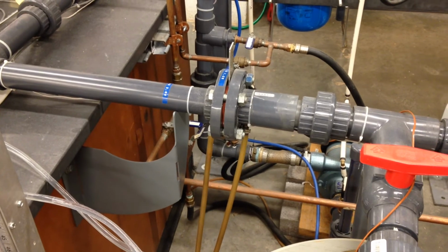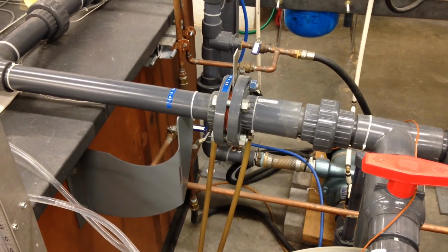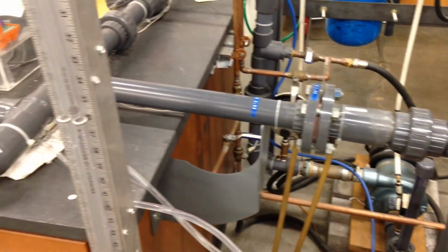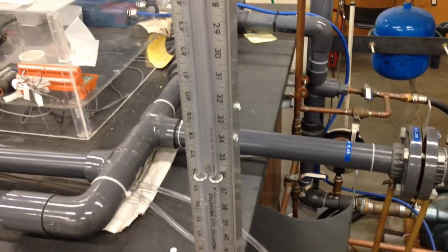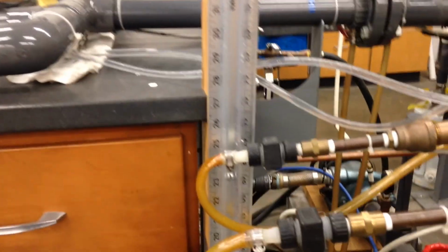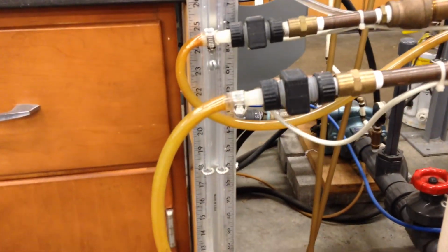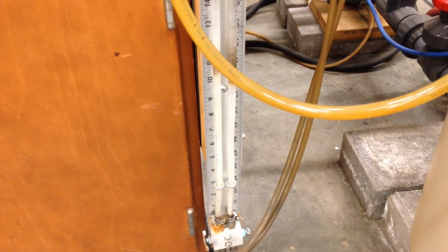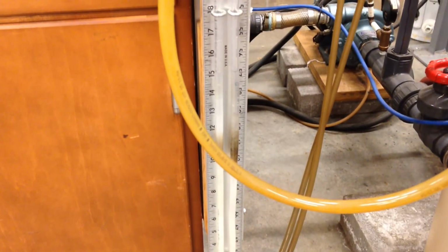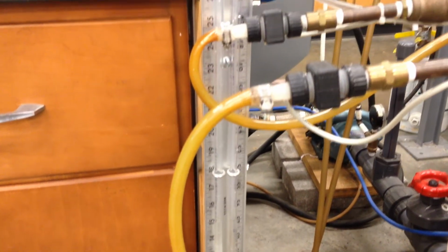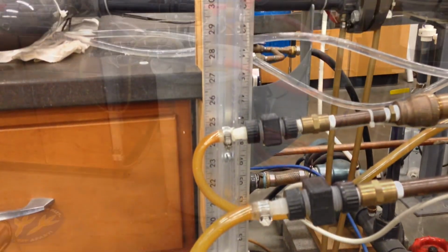This last is the second orifice. And we measure the head loss not by a digital manometer, but by a standard conventional manometer. The reason we've kept this in the experiment is to show you what exactly one looks like and how you read it, and also what it really means to say what is head difference between 2 points. That's not always an easy concept to grasp, and it's not always easy to wonder why we do it this way, but this standard manometer, I think, will answer those questions for you.